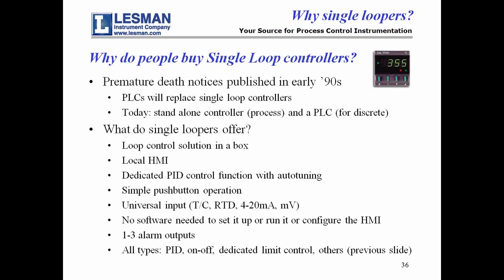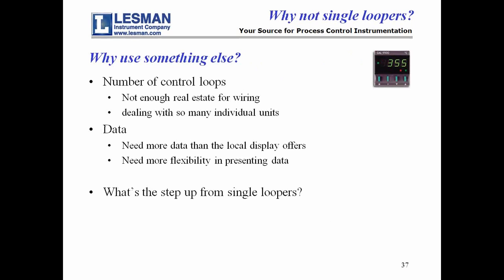Another big thing is they have universal inputs. Most PLCs have cards that are either thermocouple cards or RTD cards or analog cards like 4 to 20s. An analog card won't take a thermocouple. Most of these single loop controllers have universal inputs on them, so it doesn't matter what you've got out there for a signal coming in from the field. They typically have alarm outputs, and you put all this together, and there's still a big marketplace out there for single loop controllers because it fills the bill. Why use anything else, actually?